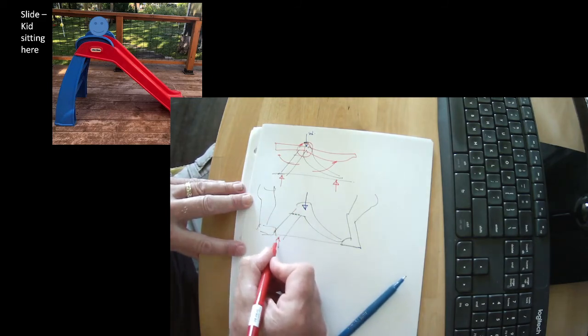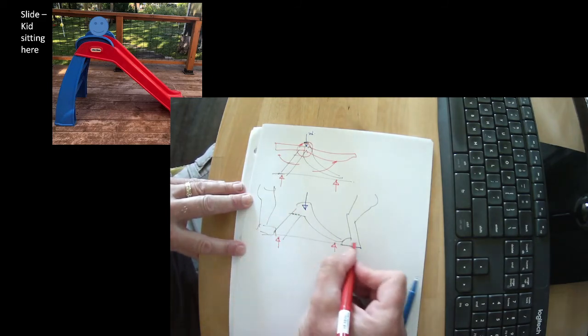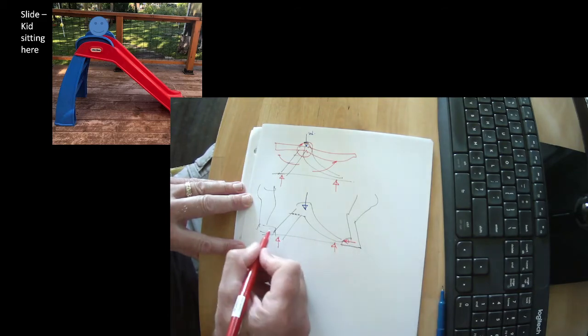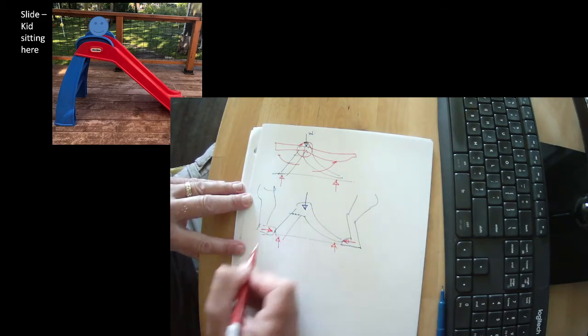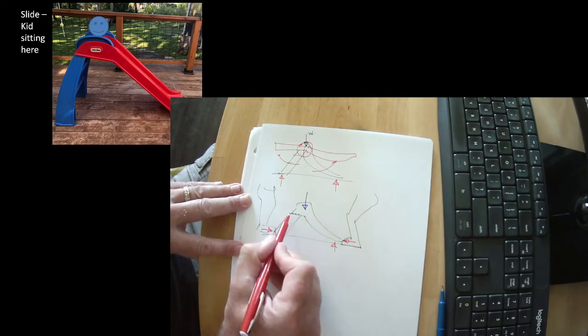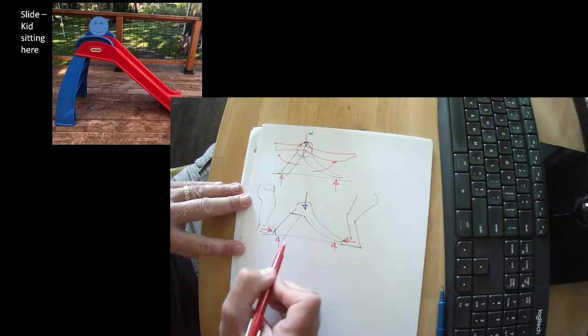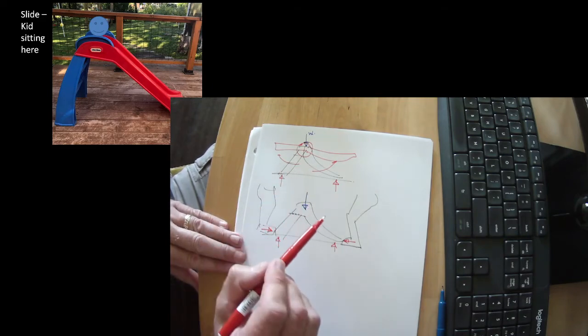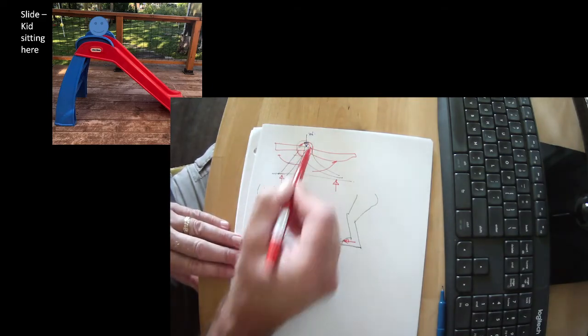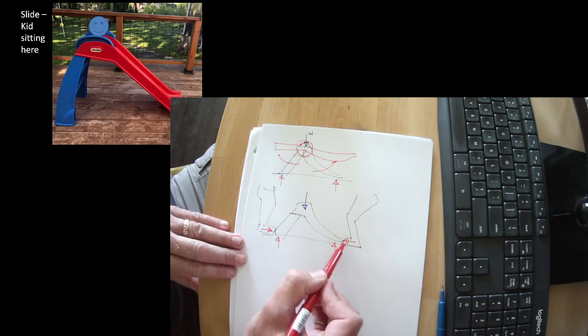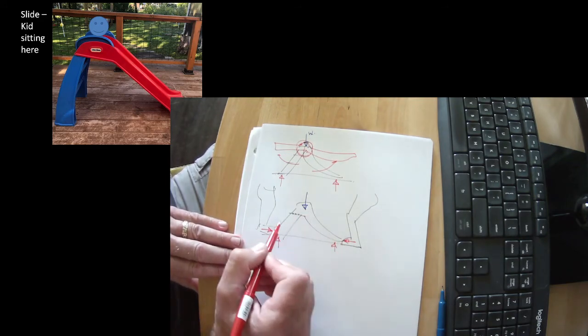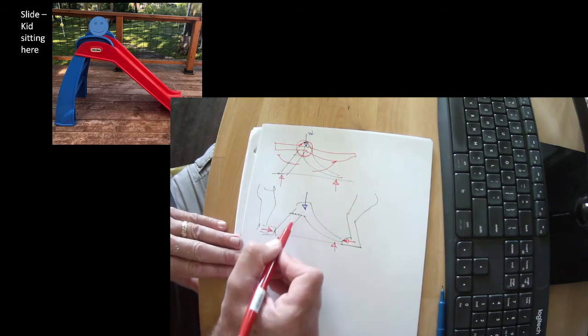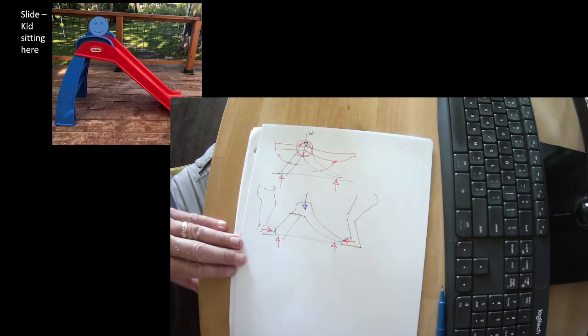We have a vertical reaction here, vertical reaction here, a horizontal reaction here, a horizontal reaction here. And even though it's broken there, it's not going to collapse. So in its normal state, it relies on the integrity of this joint. If we can resist outward thrust at the base, the load diagram changes and it becomes an arch.